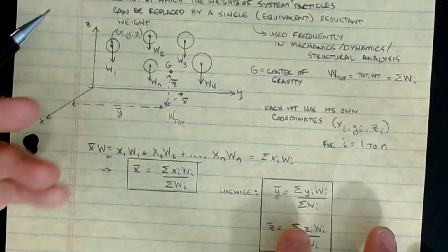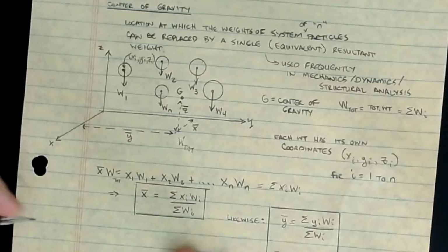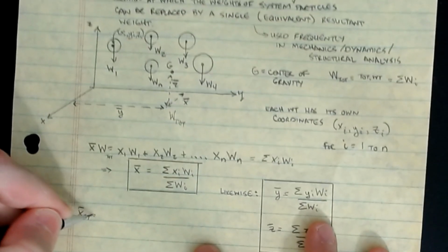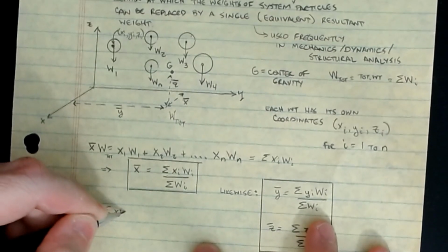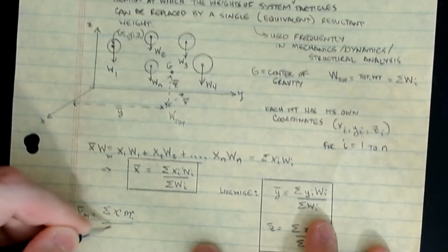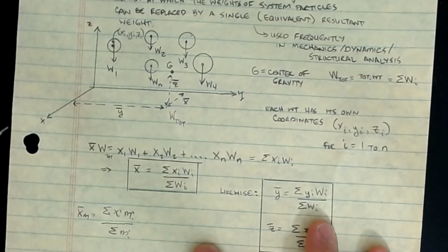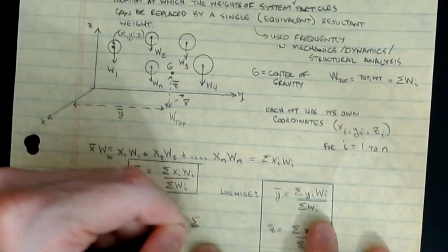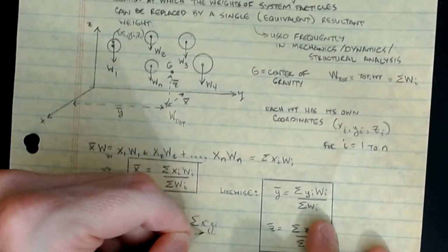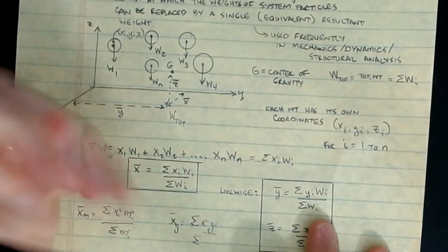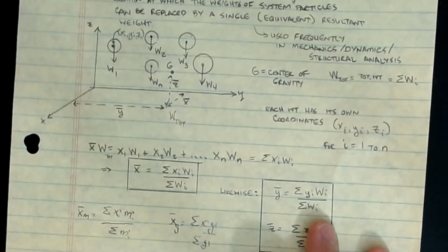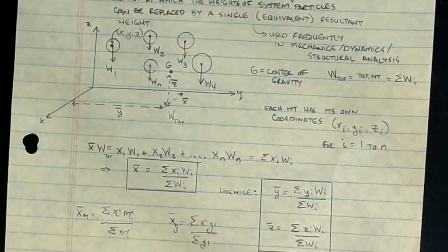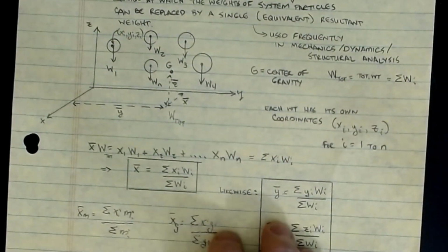And we'll show you a bunch of others that can happen. Okay, some of the others that you might see are that the x bar m, which would be for the mass, would be the sum of xi mi all over the sum of the mi. So that would be center of mass. We could do x bar for g, which could be the sum of xi gi all over the sum of gi. So all of that will start to work. And that, oops, my line didn't come in, looks something kind of like this. So it's the same form of the equation for the centroid. It's just what are you trying to find the centroid of?